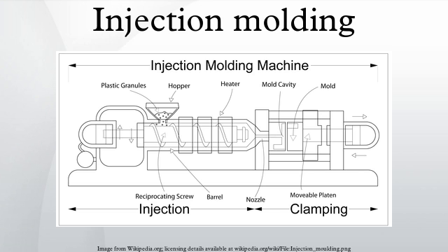Molding defects. Injection molding is a complex technology with possible production problems. They can be caused either by defects in the molds, or more often by the molding process itself. Methods such as industrial CT scanning can help with finding these defects externally as well as internally.